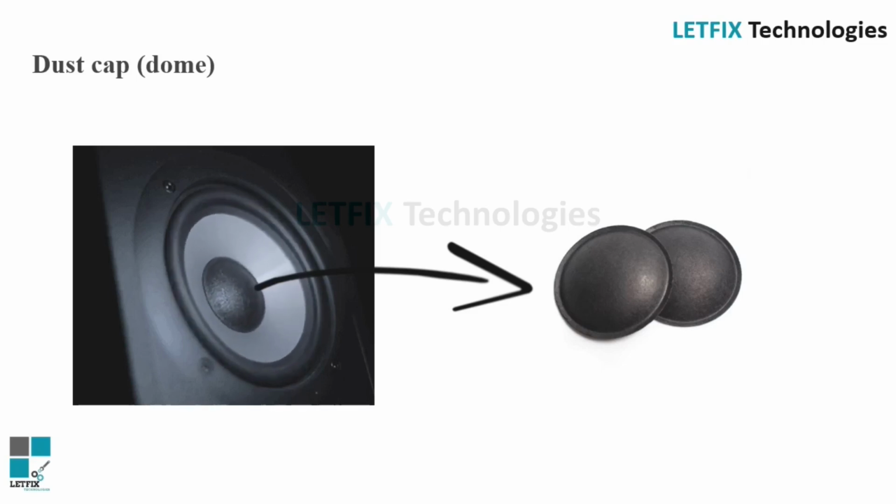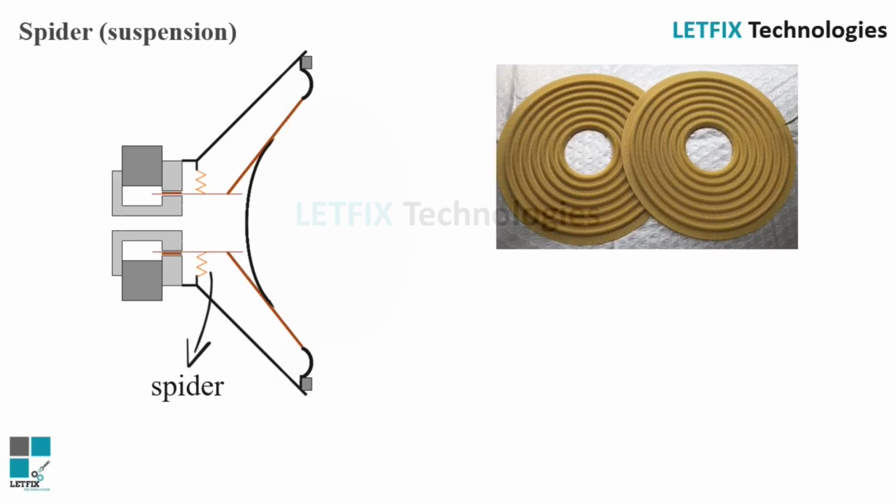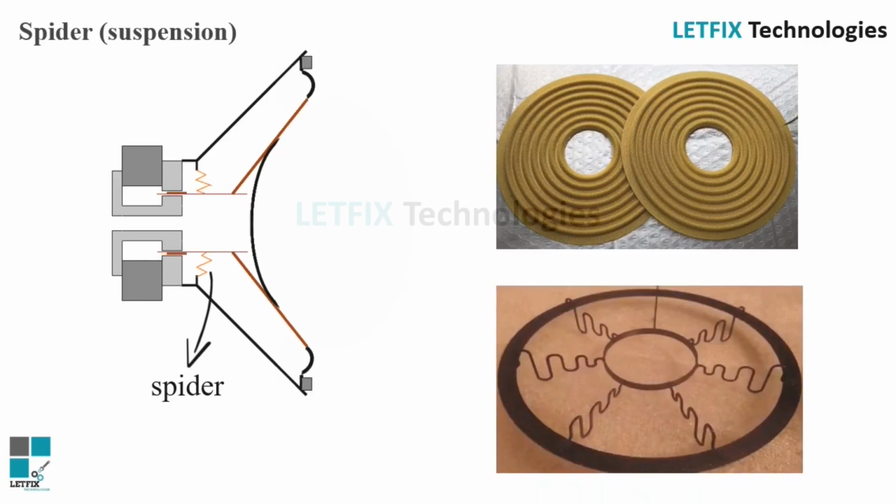Spider. Spider is a rubber-type material having an opening at the center, located between the inner rim and the outer rim. This is flexible and holds the voice coil in place, allowing it to move freely. It is not present on some lower-end loudspeakers but provides a very useful support to the coil even if it is not properly centered. Normally, the space around the coil is limited to enable the maximum efficiency to be maintained, and the coil needs to be free from touching the adjacent magnet. If it touches, it causes a rasping sound to be heard as the loudspeaker coil moves in and out.